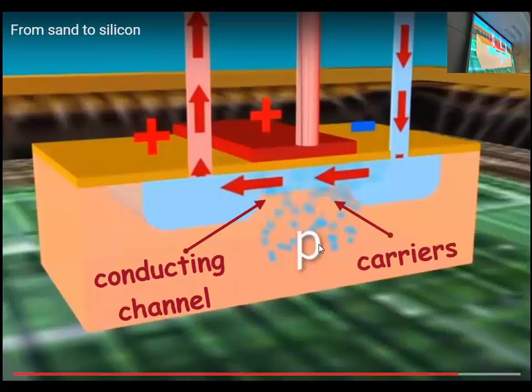So what's the point? We built this structure out of silicon lattice. We've doped these two regions. The point is that there are excess carriers, in this case P-type excess carriers, in this substrate that are available to enter what we call the channel. The channel is between the two terminals, source and drain. This is the source and this is the drain. It's just like water. The water model is pretty good, so keep with the water model. This gate is a gate for the flow of current. They'll open the gate and they can flood the field.